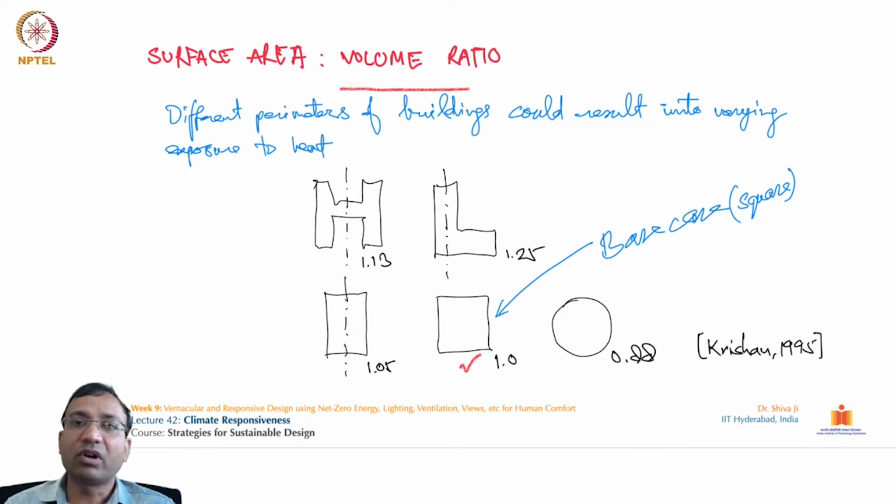Okay, so if you are living in a colder place, then it is ideal for you to increase the surface area. But if you are not living in a colder place, or you are living in a very hot place, then it is always desirable and recommended to minimize the surface area, so as to reduce the heat gain in the building. In turn, you will spend less, or in a controlled manner, on cooling that space.